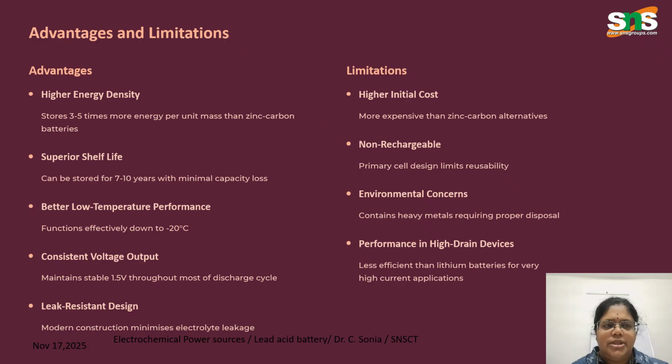Advantages and also the limitations. First, we'll see the advantages. Higher energy density: it stores 3 to 5 times more energy per unit mass than zinc carbon batteries. Superior shelf life: it can be stored for 7 to 10 years with minimal capacity loss.